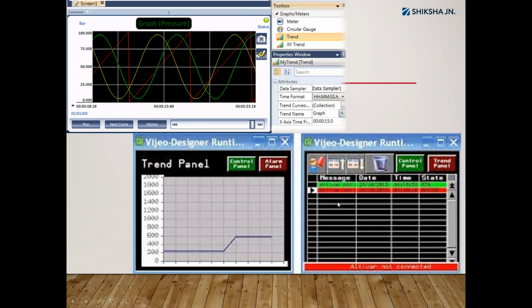Below on the right-hand side, you can see this is what I was talking about, the alarms. A tabular sheet is there: date, time, message, event, whether it has been acknowledged or not, that means it has been read or not, who the operator is, the name of that operator. And what its condition is, whether it is in alarming state or out of the alarm now. All these indications will be shown. There is no particular limit on how many alarms and how many trends can be used. You can use multiple trends and multiple alarming systems in the HMI system.